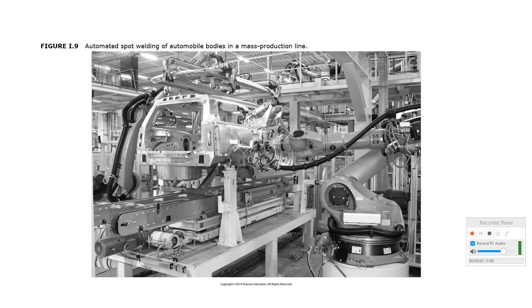This is a welding line. You see several kinds of manufacturing technology combined in order to satisfy the requirement of a simple welding. We have different kinds, if you see in here, these are stands, or we would say work holding, because this one is our workpiece. The body is the workpiece. Here you can see some kind of coordinate measuring in order to see if the car is in position. The robotic arm is coming for welding. So all of this plays a role in determining what manufacturing capability we have.